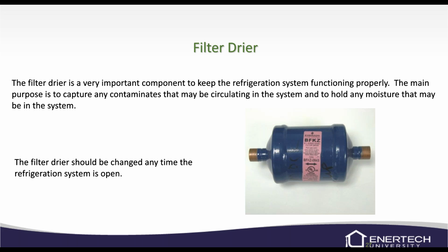Obviously, it's there to keep any moisture out of the system, and it's really the only way to collect that moisture if it gets into the system. So make sure we're using a bi-flow filter dryer and don't torch it out.